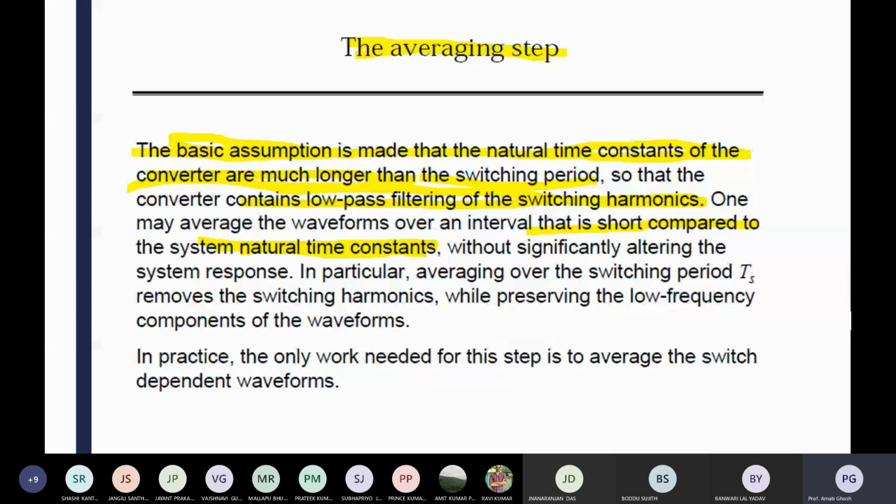Okay, that overshoot is too high. So you can consider that in your calculation, you can say that your maximum tolerable percentage of overshoot is 20%. Okay, suddenly what happened: if you increase the gain, that means the proportional gain, the percentage of overshoot comes beyond 50%.